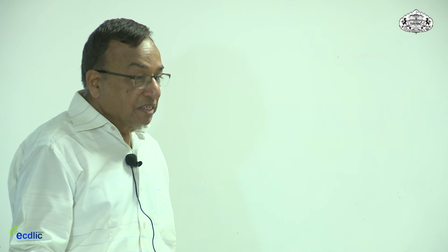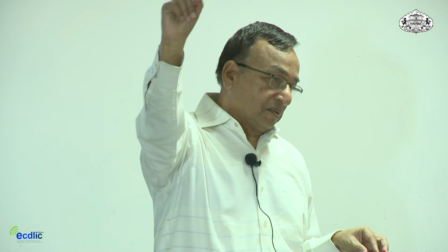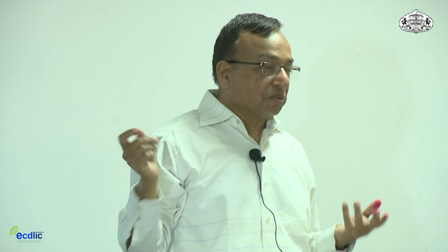It gives input to guidance, where there is a guidance law which tells, from the immediate location to the final point in the orbit where it has to reach, how it is going to reach there, what is the most desired optimum path it is going to take to reach that point.